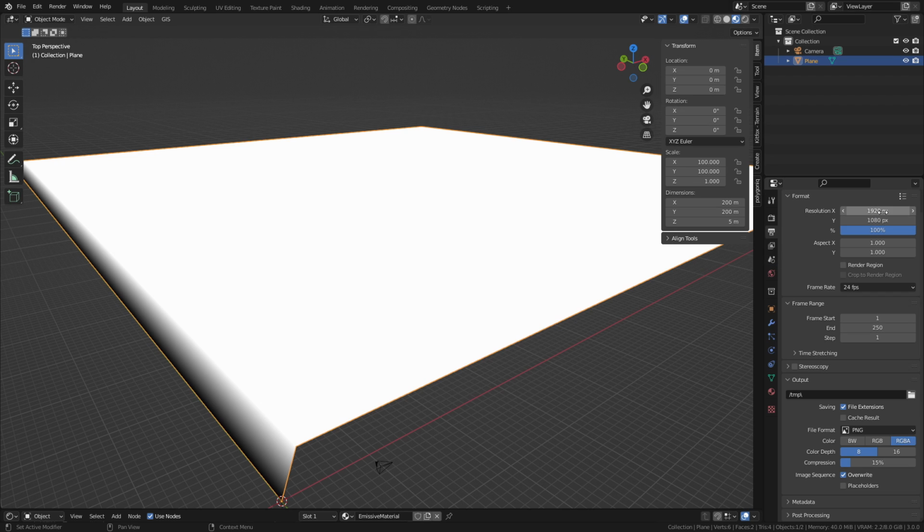Our resolution, we are going to change to 2049 by 2049. And again, if you were using a rectangle, change that to 2049 by 1025, or if you started out 4K, it would be 4097 by 2049. Remember, it always has to be a power of 2 plus 1 for your height map dimensions.